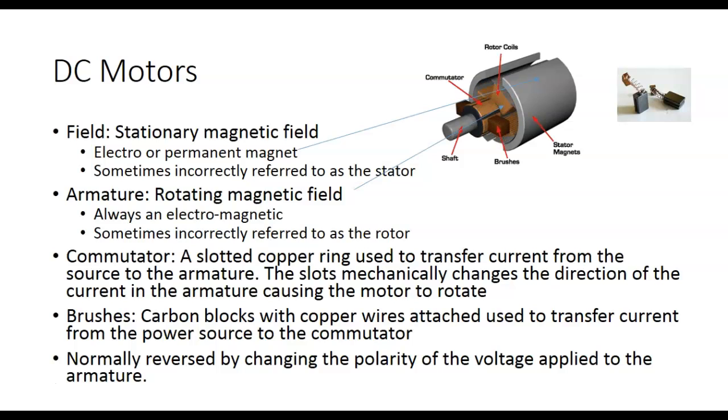By the way, on your alternator, it's spinning an electromagnet, so you've got brushes on that thing too, and eventually it will wear out. And sometimes you can replace them, sometimes you can't. I was driving a Dodge van down to Gulf Shores, and the alternator went out on it. I popped the brushes out of the thing, which was real easy to get to, and replaced the brushes. You know how much the brushes cost me? $2. How much would the new alternator cost? A lot, yeah. But that's back when they were replaceable. Most of the time you can't even get into the alternators anymore.